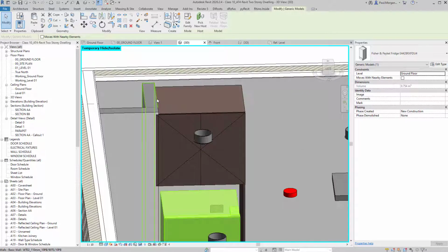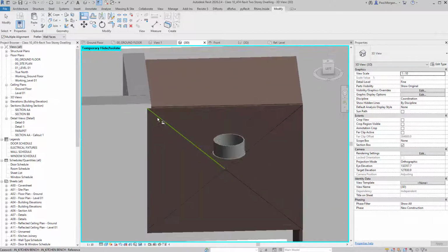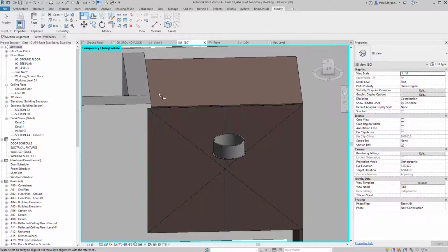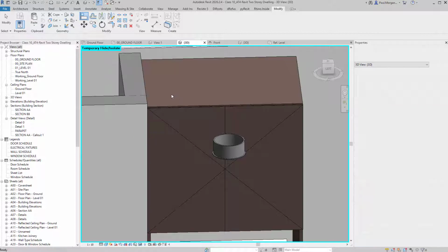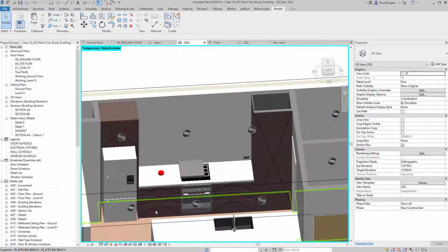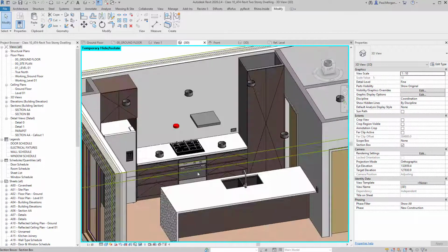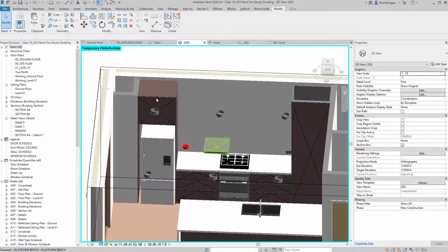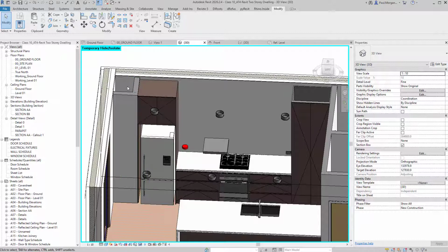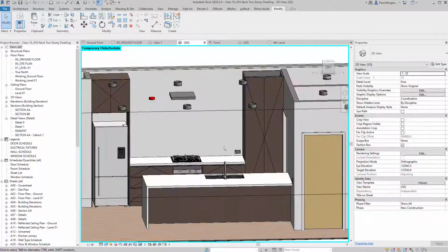The other thing as well is I've got some conflict between this little nib wall and the joinery, and I'm going to move the wall back to meet the joinery. So I'm just going to go there and there, and there we go. The reason why I've done that is because this joinery is all standardized sizes really, and it's worked out quite nicely in terms of being even numbers. So I don't want to mess around with the joinery just for this nib wall, which would only be hiding some sort of surfaces anyway. There's nothing structural about it. There's no reason why it can't move.